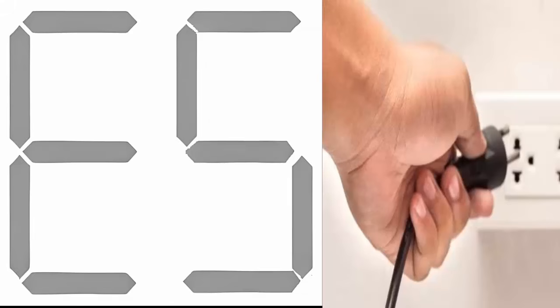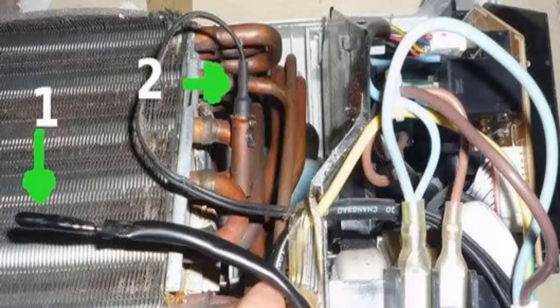In this video, we will delve into the explanation of the E5 error in various brands of air conditioning systems. Before delving into issues related to this sensor, when a unit displays the E5 error, it is recommended, as a first step, to disconnect the device for several minutes, check the position of the temperature sensors, and visually inspect the condition of the sensor power cables.